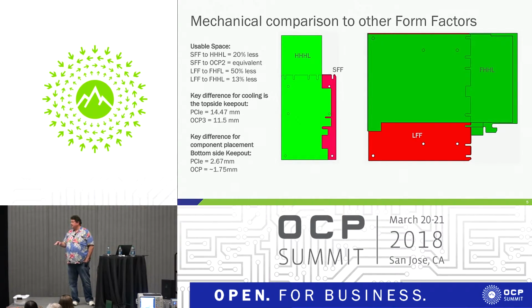The other thing, and he mentioned this, but to me it was really critical. If you've designed a system or card around 2.0, there's like 13 different Z height keep out areas, so you have to be able to move parts around, and that part is 0.1 over there. And so this is a nice, very simple shaped keep out that I think will ease layout guidelines for the NIC vendors and make it much easier to fit it into a server.